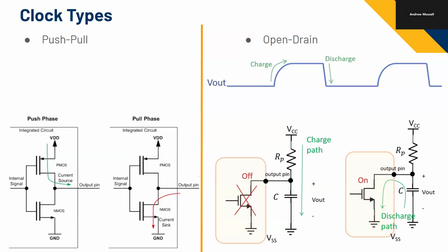We can go into this more, but once you start looking into MOSFETs, there are capacitors all over the place in this thing. There's a capacitor gate to source, there's a capacitor gate to drain. This itself is a capacitor, that's why it's drawn like that. So there are a lot of capacitances to charge, which is basically what we're driving.